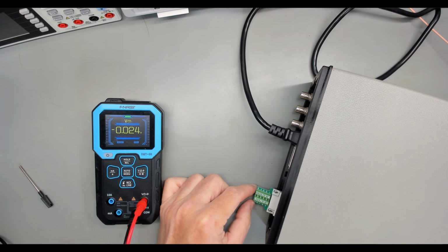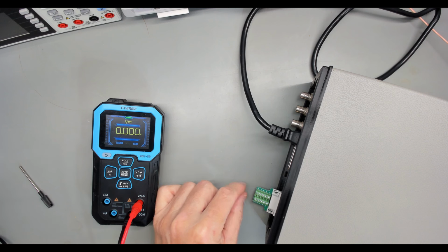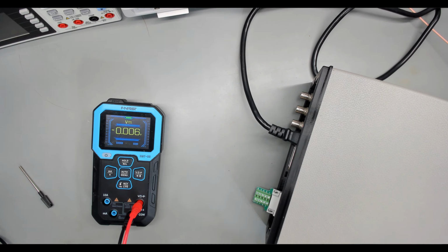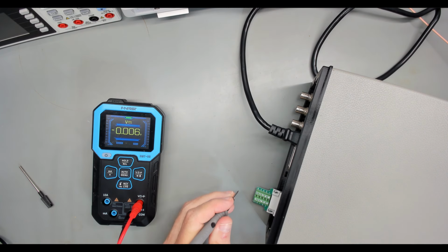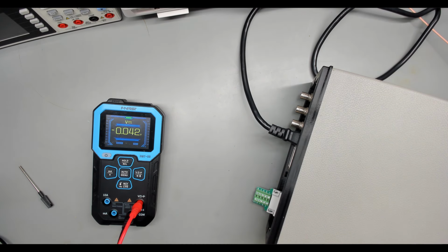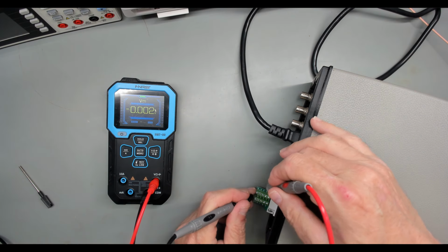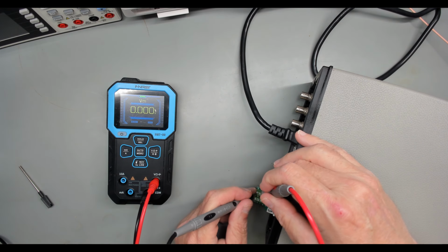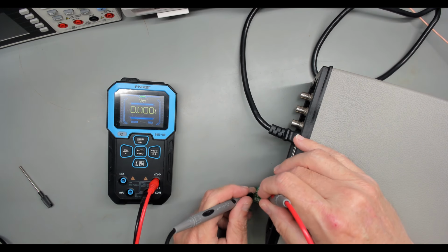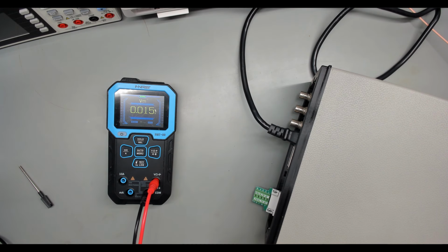I pulled out some little DB9 COM port terminal strip units that plug in, which make it a little easier to work with. It's kind of hard to get on the little pins without shorting things out, and you don't want to do that. So I'm going to stand up here so I can see what I'm doing. We're looking at the voltmeter here. I'm going to get on pin 5. What I'm going to do is look at pin 3, and see if I've got a negative voltage on pin 3. Oh, let me turn it on, that would help.